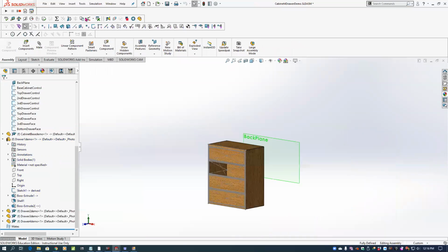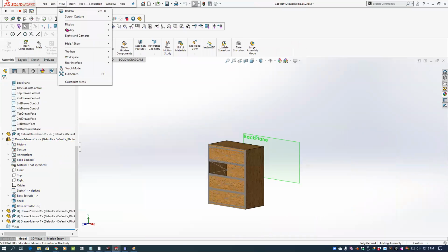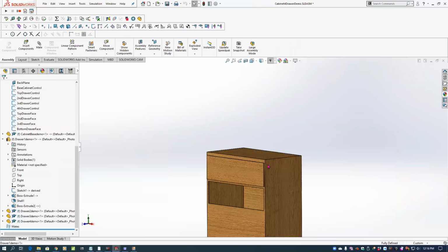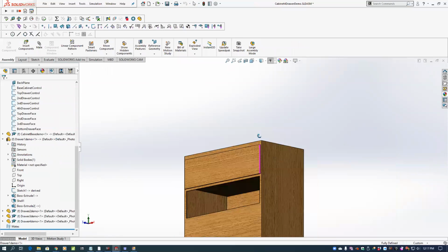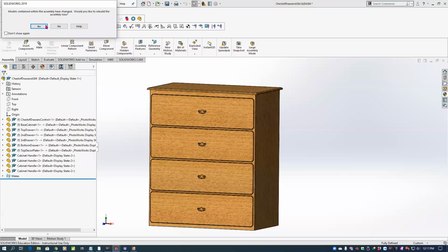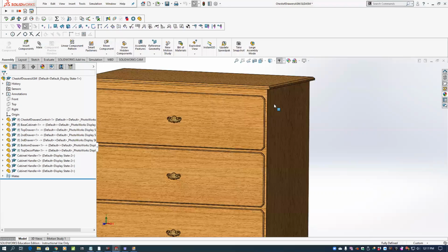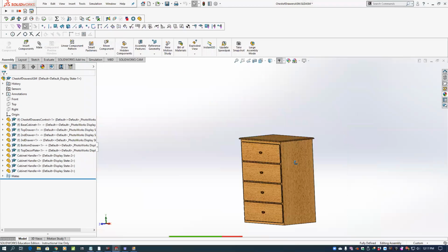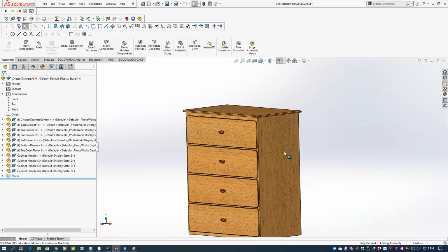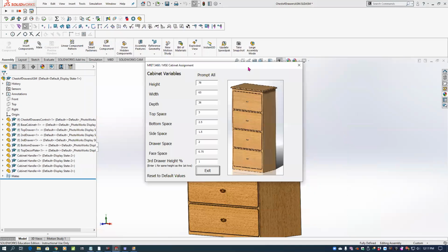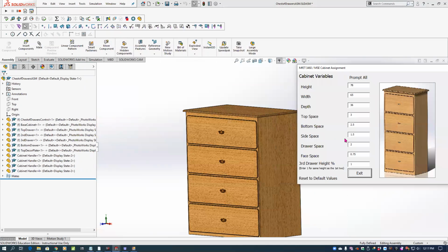And we can continue on with that kind of process, creating each of the drawers. And you could add additional features on there like I have in my chest of drawers, where I've added handles, added chamfers, added different cuts and so on, those individual pieces to make them more realistic. Then once you have your cabinet done, and if you control it with a macro, which I've done here, I've controlled the text file with a macro.